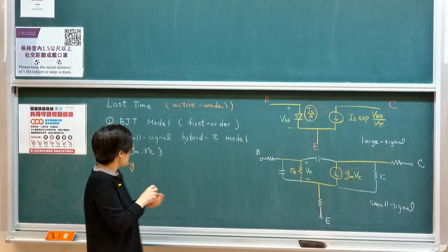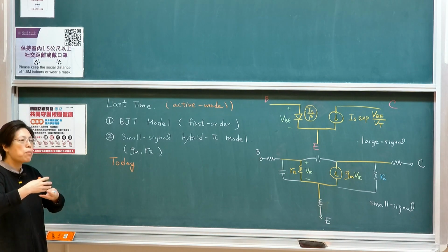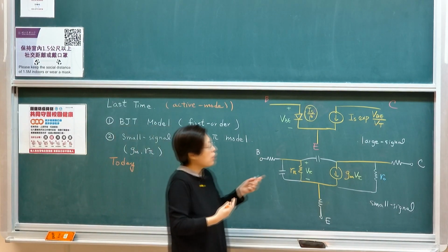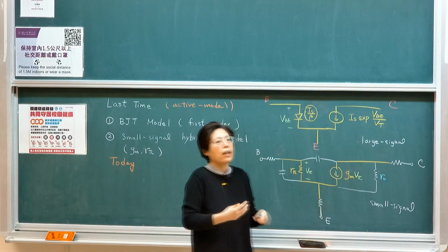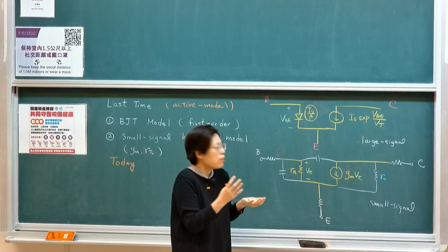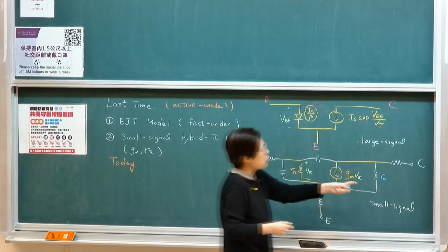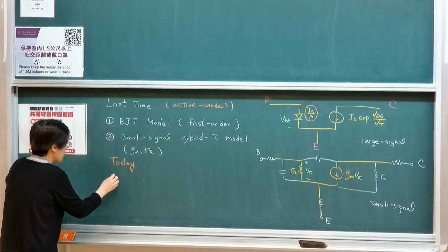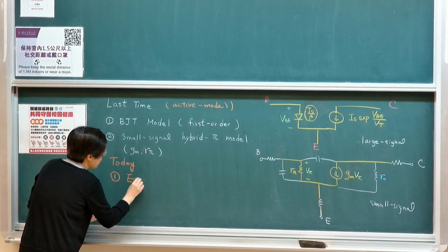So today we're going to address additional, I wouldn't say too much into second order analysis, but the non-ideal factor when this current source is no longer ideal, which means that it's no longer simply a current source, there's other dependency, which would then introduce what is called output resistance. This actually comes about because of what we call the early effect.